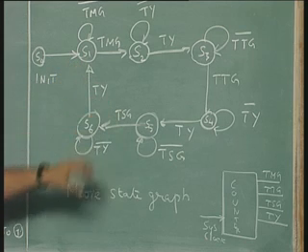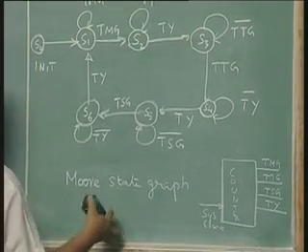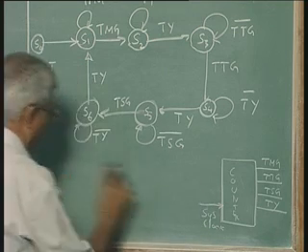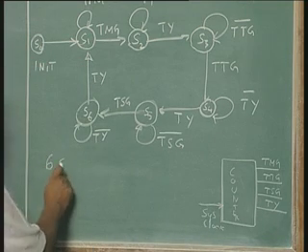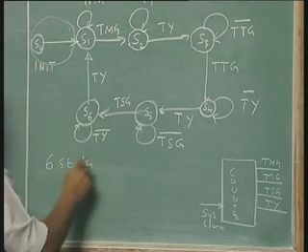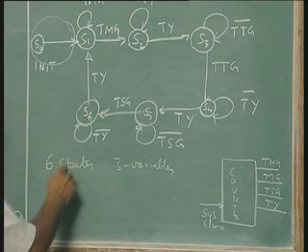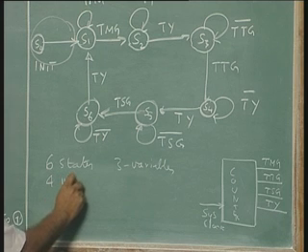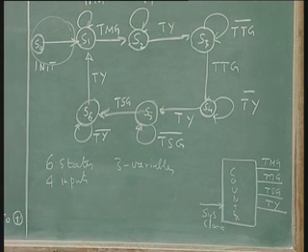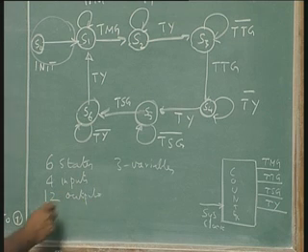So this is the state graph with 3 variables, because there are 6 states, leaving out the init. Without this there are 6 states, that means 3 variables, 4 inputs in addition to state inputs, and 12 outputs, 4 lights each, 3 colors. But actually, some of these 12 outputs are redundant.